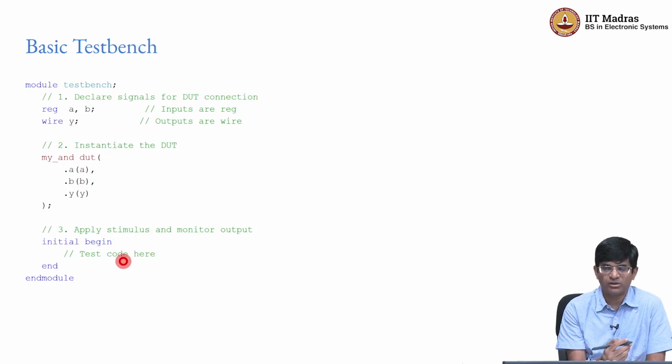Think of it like you have a breadboard and you have multiple different inverter chips. They all behave exactly the same, but because they are getting different inputs, they are going to show you different outputs. This is exactly what's happening, and in order to reference something on the breadboard, you would use some kind of a label or name associated with each of those individual chips. That's exactly what this label out here is doing. It's something that you get to choose, you can put in anything that you want, and finally it allows you to map all the inputs and outputs.